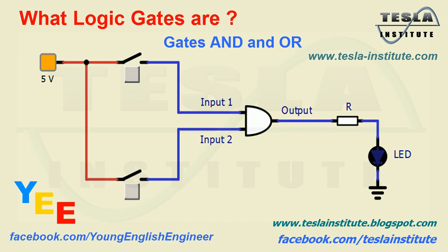So we're going to play this circuit, and as you can see, no current is flowing through the LED on the output. It's not letting any current flow through. And that's because our logic inputs to this logic gate are completely off. Both of them are on a logic low or 0 volts. Now if we turn one of the logic inputs on,